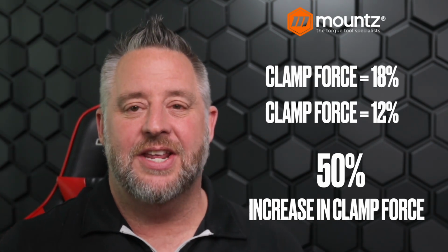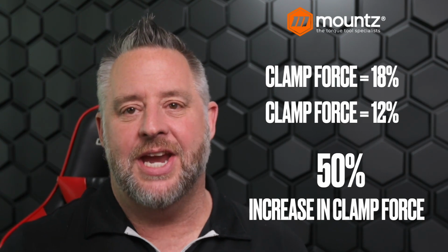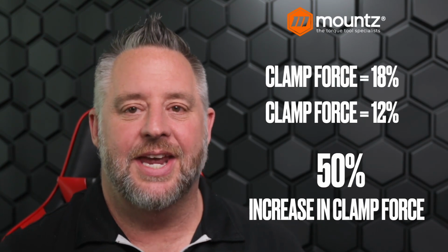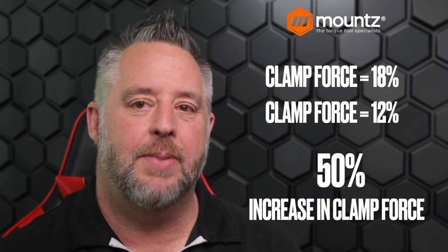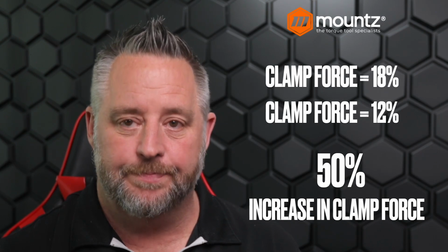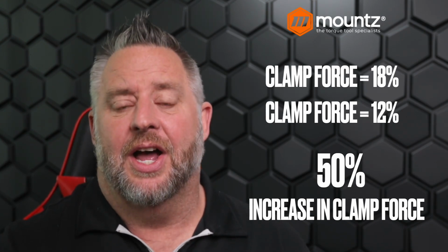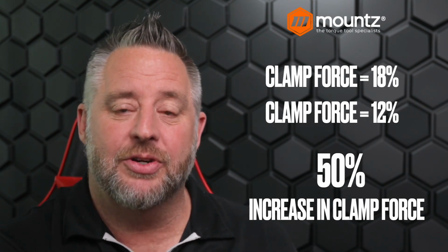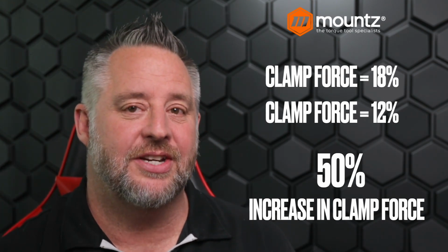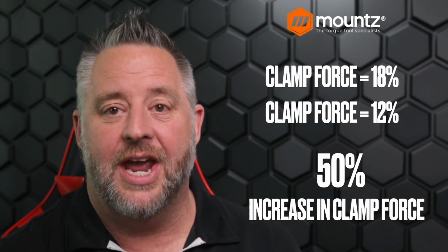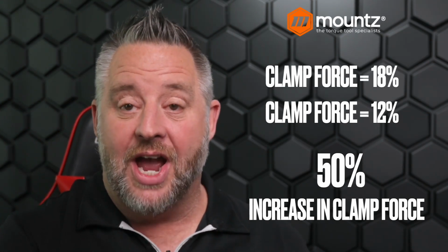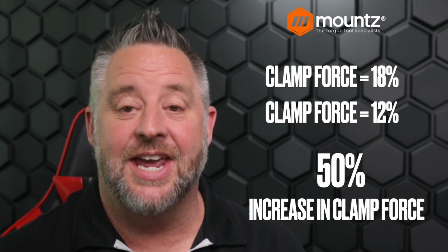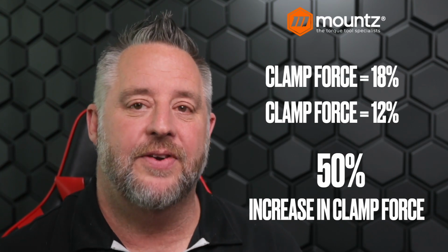And so you can really see that any type of change to the process or to the material can cause a great deal of impact to the actual clamp force. Now, if we did this in reverse and we added an additional 10% because the characteristics of the head friction caused it to rise, then we would be reducing our clamp force again in that area of about 50%.